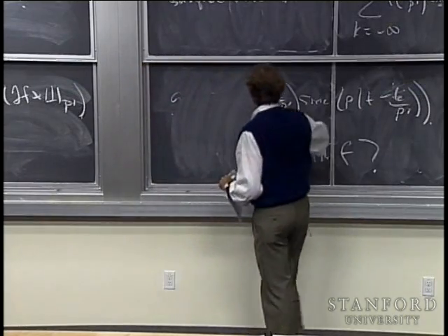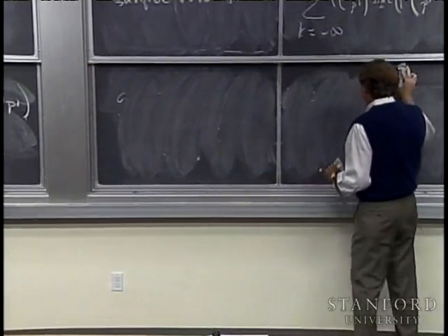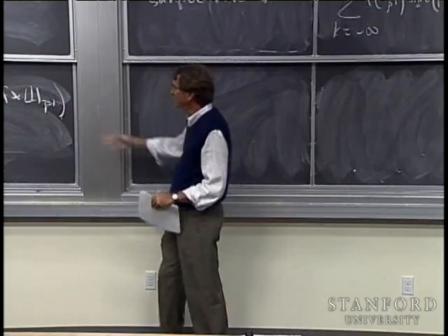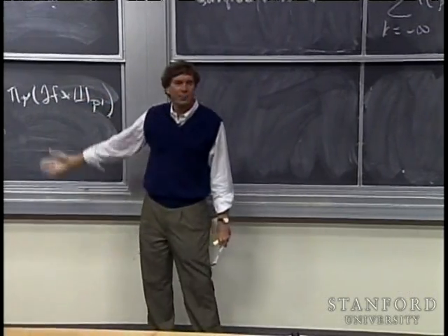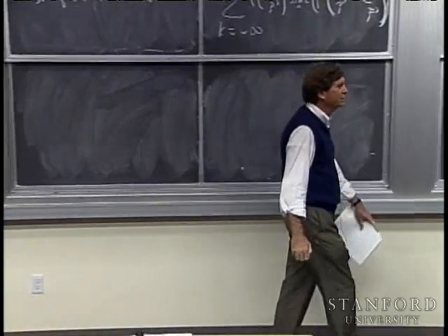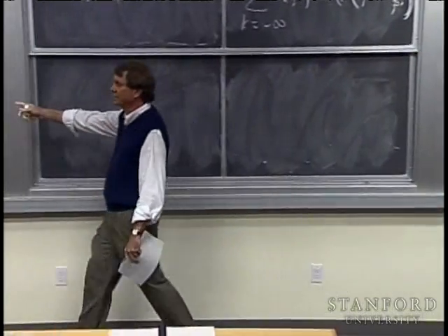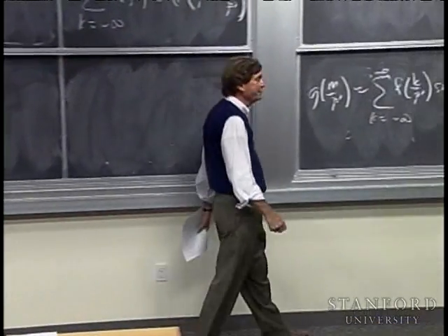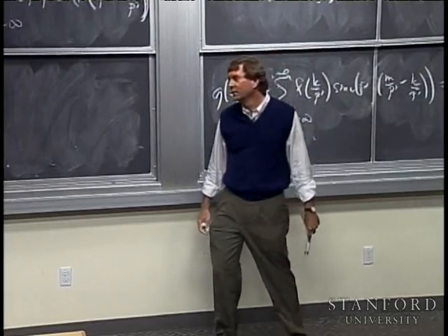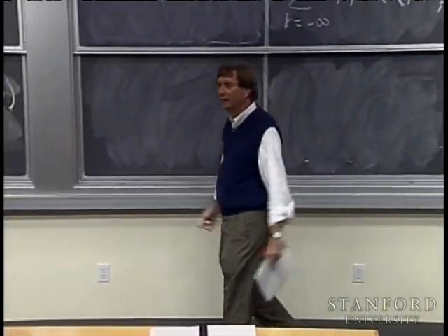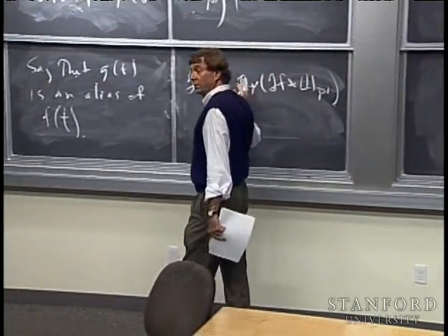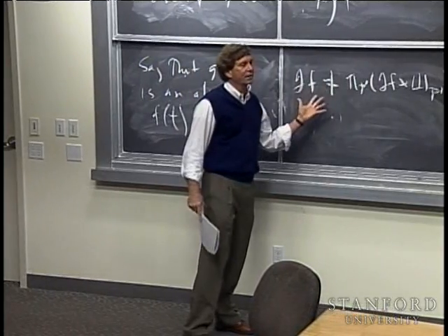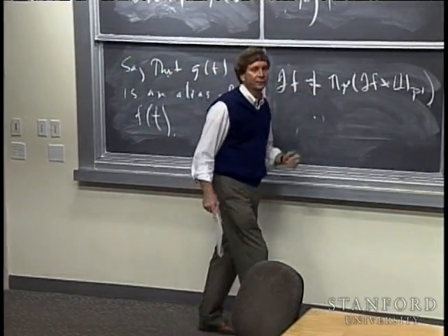So again, I want to stress this: in aliasing, it's not that you've done something wrong. You have reproduced a signal that has the right sample values, but it's not the signal that you hope to reproduce because of this. It's not that you made a mistake somehow, or maybe you have, but you haven't sinned against the forces of good. You're deriving the sampling formula, pursuing the argument the natural way, but you're not getting back the original function because this equation is not satisfied.